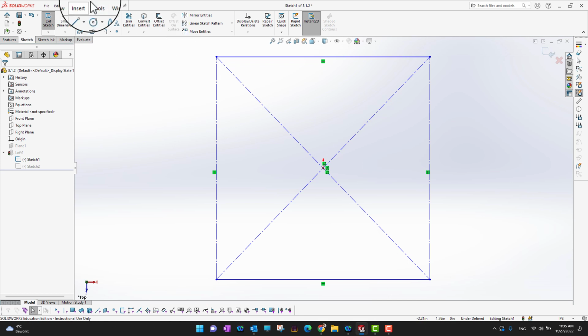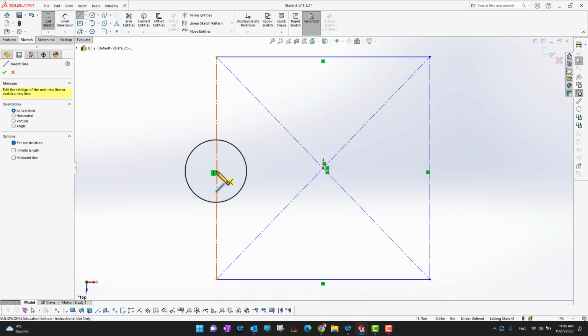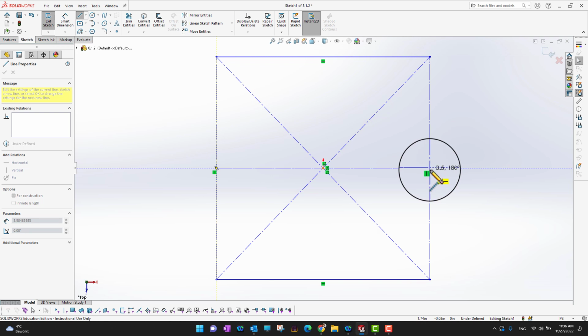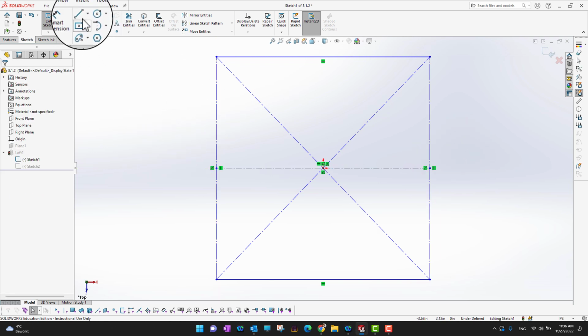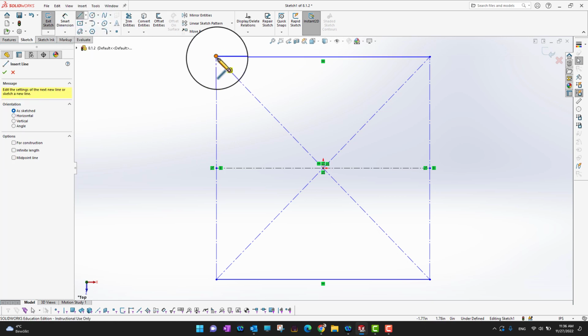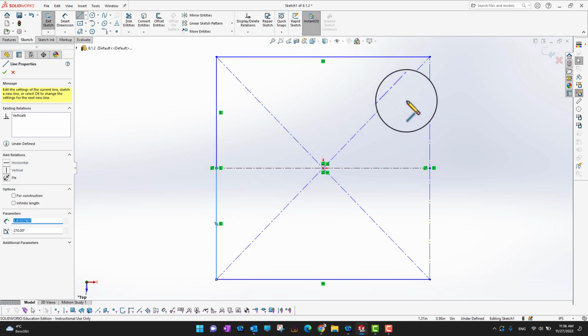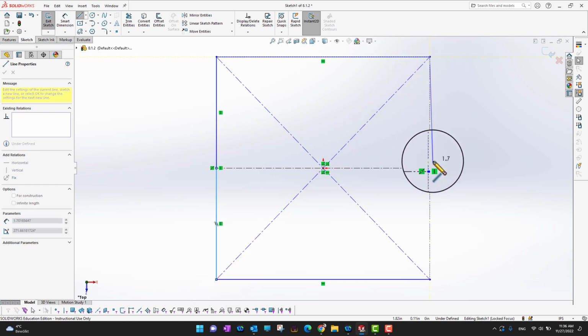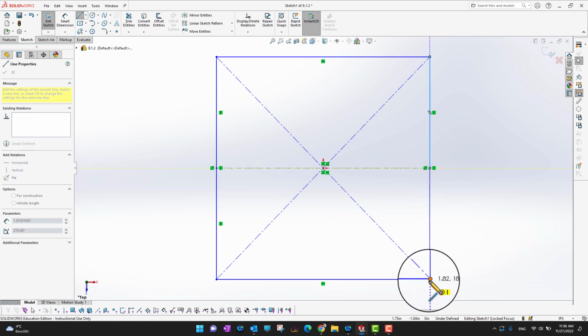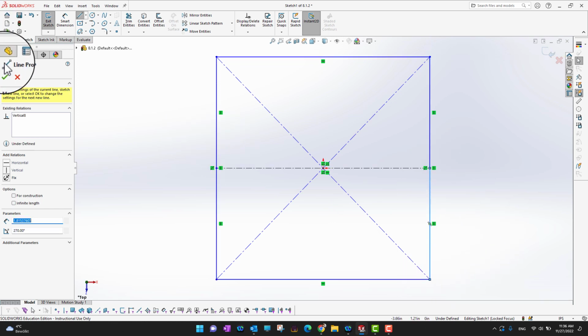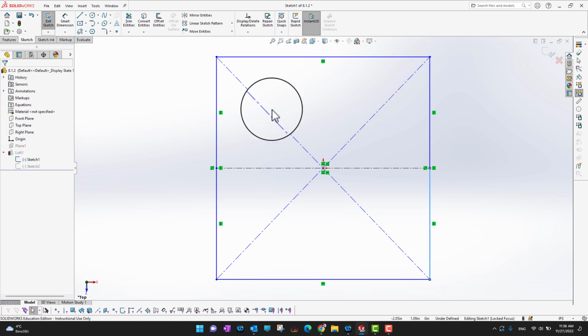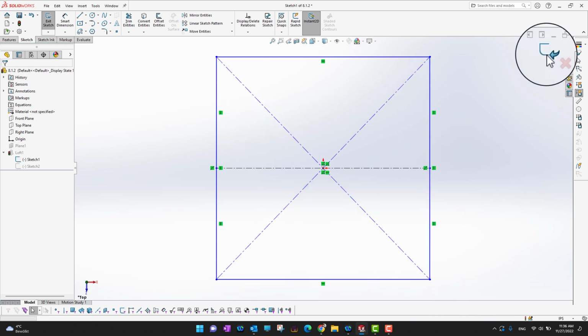Okay. And then what I can do is I can just go into the center line command, and I can draw a center line from that center point till here, like that. And then I'm gonna sketch a line from this point till center, and then from center to this point, and then again from this point to this point, and then from this point to this point. And then I'm gonna click the green check mark. Okay, so in this way, although still I have a square, I have 6 points right now. 1, 2, 3, 4, 5, 6. So let's end the sketch.